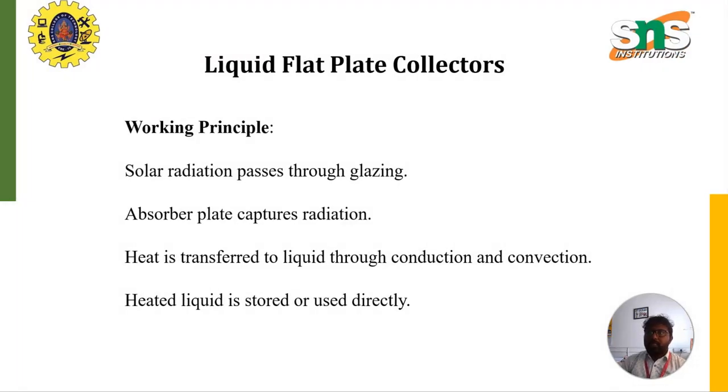In heat transfer in a solar dryer, there is radiation, convection, conduction, evaporation. In radiation, the absorber plate captures solar radiation, and in convection, hot air transfers heat to the product, conduction through the structure and tray, and evaporation, the moisture moves from the product to air.